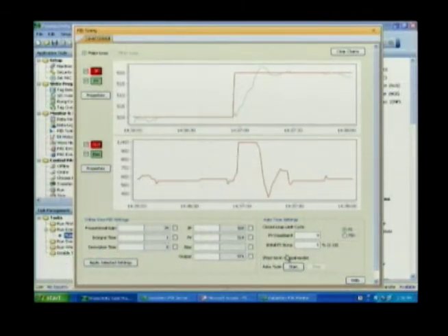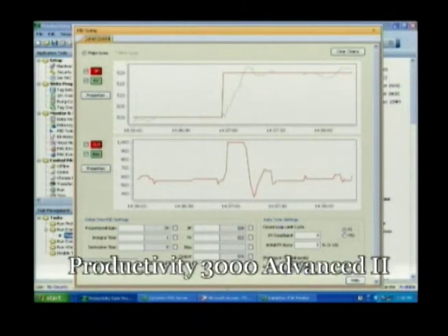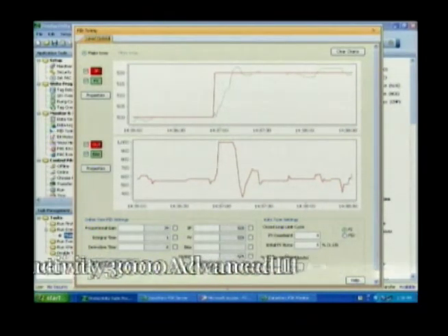For sure, the way we have this system, we can pump the tank up, but we actually are using gravity through a drain valve or a siphon tube to drain it, and we've put a petcock in there so we can adjust how much drainage we get. So that's another variable, and basically if I tried to tune this again, depending on where I set that petcock, I'd probably get slightly different values for the proportional gain and then the integral time.